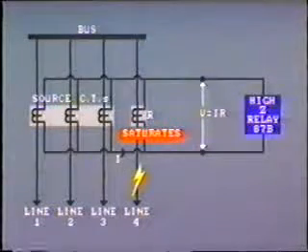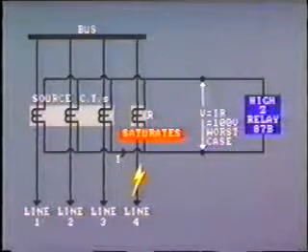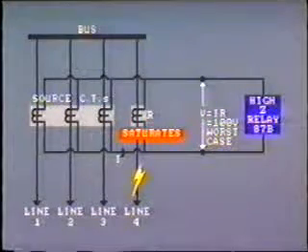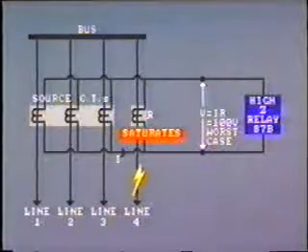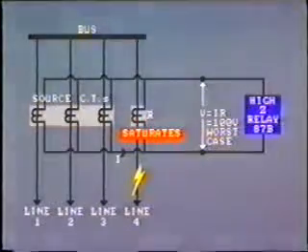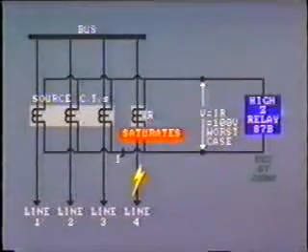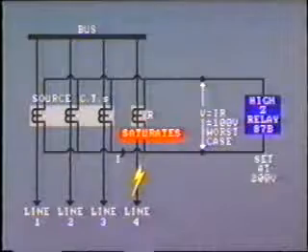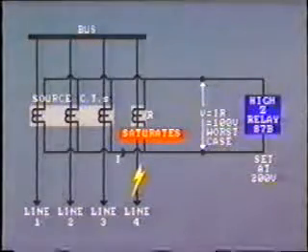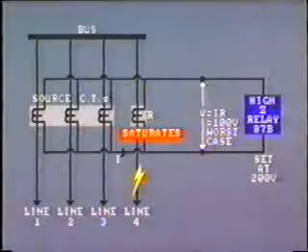Let's assume, for example, that the worst case or highest saturation voltage that could be presented to the relay was 100 volts. We would not want the relay to trip for this value. Therefore, we would desensitize the relay by setting it with a safety factor of 2 or 200 volts. The safety factor would have little effect on the relay's pickup for internal bus faults. Because of the importance of the bus in system operation, some installations include a supervisory circuit, which allows the operator to check the integrity of the bus differential protection circuit.